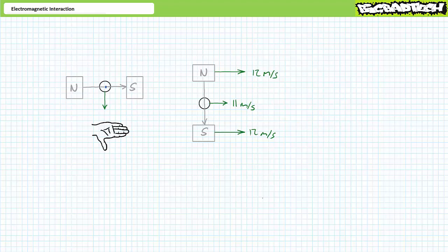The second scenario is admittedly a little odd. The magnetic field is oriented north to south, top to bottom, but it's not stationary. It's being moved rightwards at some speed. The conductor is also not stationary. It's also moving rightwards, only at a slower speed. This ultimately results in the magnetic field catching up and passing the conductor. When it does so, it's almost like the conductor was standing still and the magnetic field moved rightwards. Alternatively, this would be equivalent to keeping the magnetic field stationary and moving the conductor left. Either scenario results in relative movement between the conductor and the magnetic field.